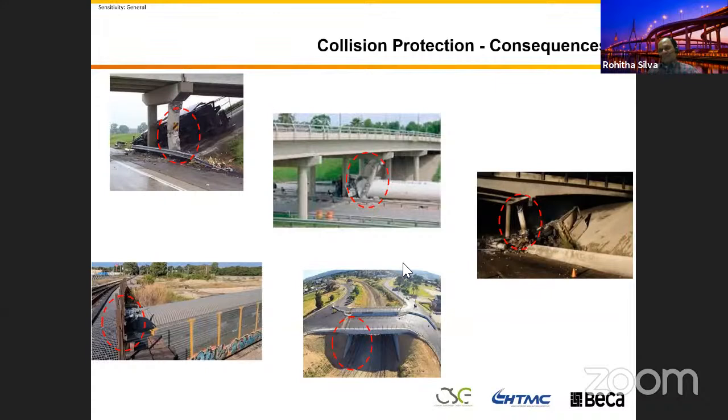I did this once or twice, but I think you can do a risk assessment and justify on paper, but in reality, you can see in this picture, it could happen. You can't prevent that. There is no zero probability, sorry, that you can say it's not going to happen. Even if there is a 1 in a million chance, if you convert the traffic into a 100-year design life, you will get a few hundred trucks that could hit one of these piers. Therefore, you need to make sure that you protect them.